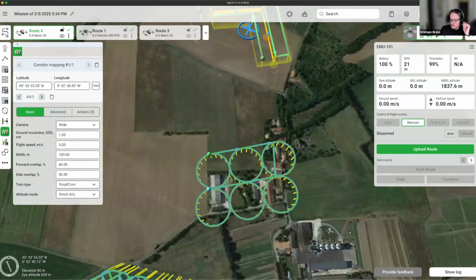And also, I've seen that even from quite limited data sets, it can capture the 3D geometry on the ground better. Of course, your mileage may vary, like I said, because of the high amount of parameters that you can adjust here. But I really believe that if you tune the parameters right, then you can get better results than you can with oblique missions simply planned on the DJI's controller.